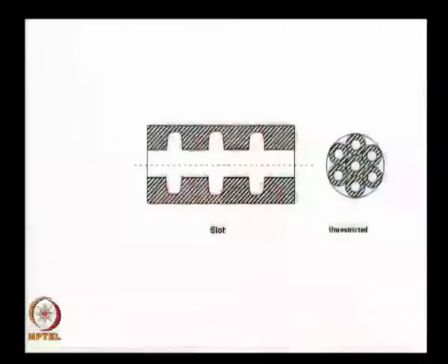I show a 3-dimensional surface over here which is a slot, and it continues to burn in this direction, in this direction, but the problem is a simple geometric problem. I want to find out how this initial burning surface area, the perimeter into the length, keeps increasing as the regression of the surface continues.